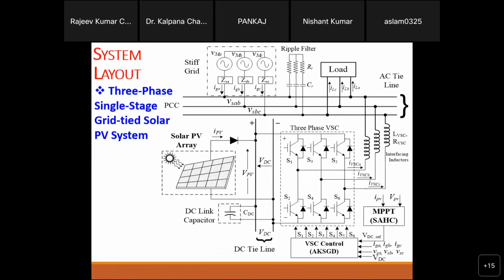Okay. This is not only for the nonlinear side. Also, we can generate the reactive power. What we will do, we will take the grid current and grid voltage, right? And then we will intentionally generate one signal which is 90 degrees phase shifted with the grid voltage. So the 90-degree phase shift means what? That is reactive. That's it.